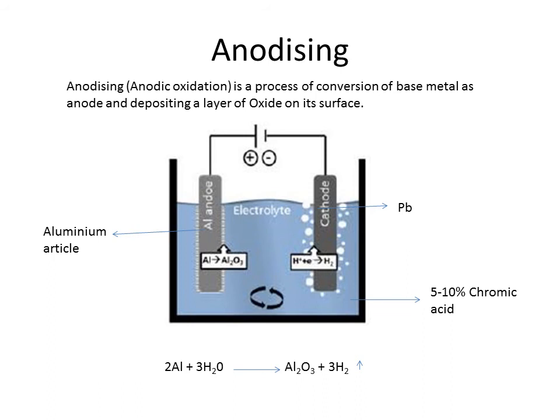Once an aluminium oxide layer is deposited on the surface of the article, after obtaining a suitable thickness, the anodization process is stopped, and then we have to take out that article, and it is completely dried. After drying it, it is dipped in a suitable coloring agent for about 20 minutes, and after obtaining a desired color which looks very attractive on the surface of that anodized aluminium, it can be used for various applications.